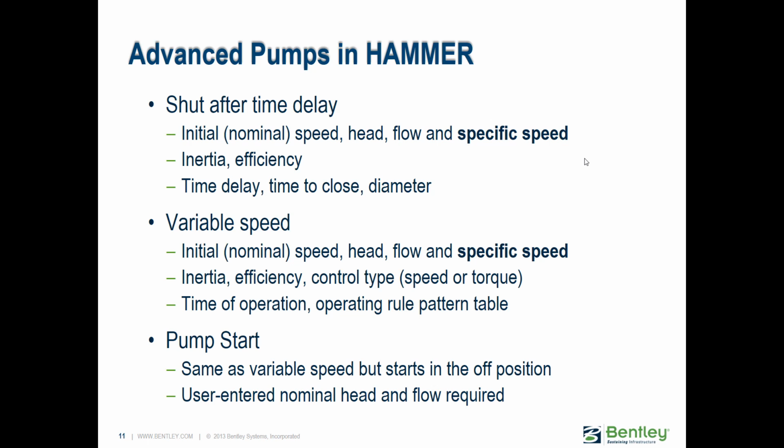Some advanced stuff. So these are some of the other different types. I've already touched on this a little bit. Shut after time delay. So you're entering all those things we just talked about, and you're entering a time delay, like 5 seconds, which means 5 seconds into the simulation, the electrical torque applied is dropped to 0. You also have an input for a time to close. So you have the flexibility to say that in addition to shutting down, you might have a check valve built into it, or maybe you have a control valve that closes at some point between the start of the simulation and whatever time that you enter.